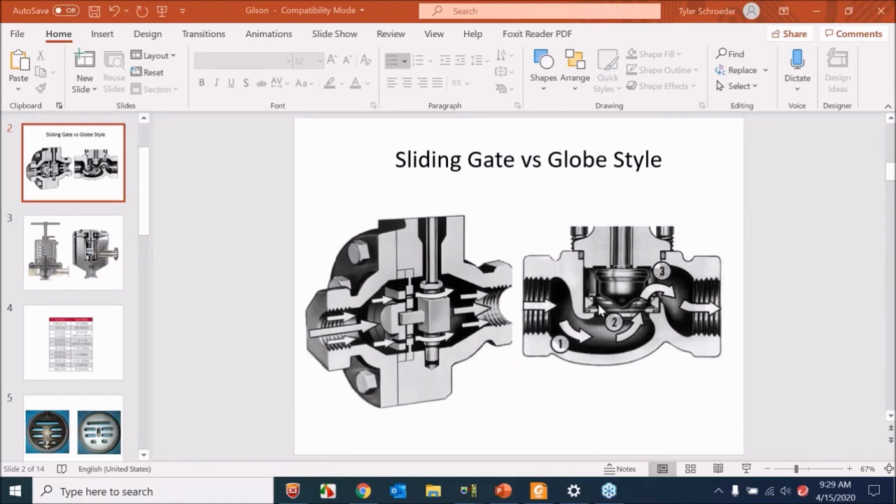What that does, other than beat the valve up when we oversize it, right? We're at 5% control range. Other than beating itself up and not lasting as long, we also get more erratic control. Meaning, if we're trying to hold 50 GPMs downstream or 50 PSI, whatever we're trying to control, that reading is going to fluctuate more than if we properly size the valve.